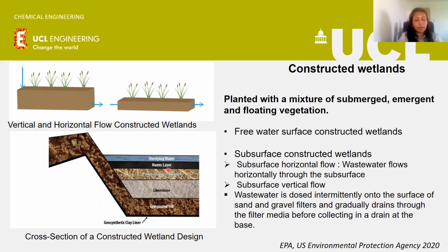So this is very important to note. A lot of planning goes into it. That is going to dictate the performance of these constructed wetlands, and it's a subject of very detailed study. So whether you have vertical or horizontal flow, how you have the different layers of rocks and materials, the rate at which you percolate down the wastewater, and how you treat it before it is drained into a place where it can be stored.